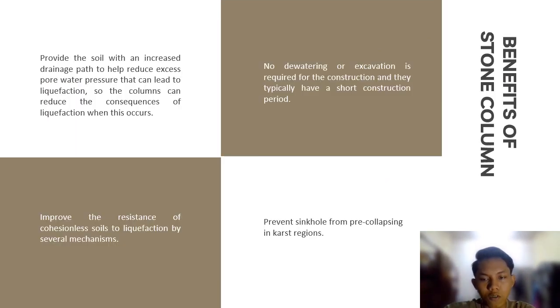So, for the benefits of stone column, number 1 is provide the soil with an increased drainage path to help reduce excess pore water pressure that can lead to liquefaction, so the columns can reduce the consequences of liquefaction when this occurs. Number 2 is no dewatering or excavation is required for the construction, and they typically have a short construction period. Number 3, improve the resistance of cohesionless soil to liquefaction by several mechanisms. The last one is prevent sinkholes from pre-collapsing in karst regions.